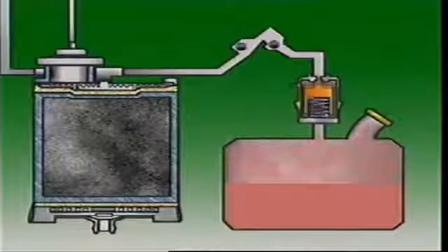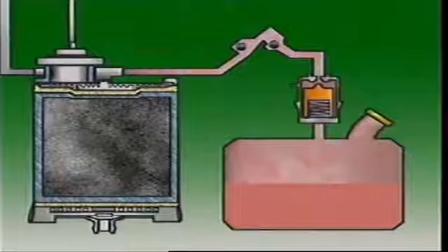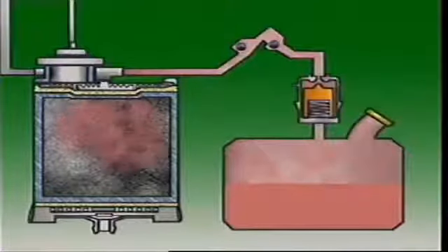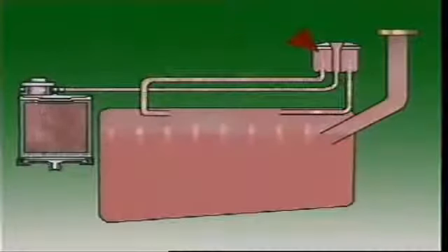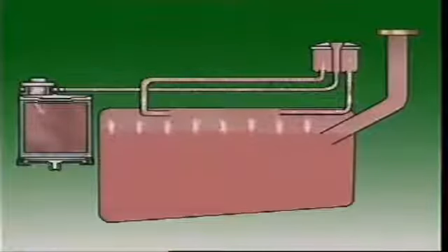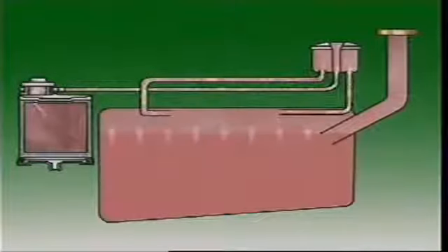This valve opens when pressure starts to rise and lets vapor through, but not liquid. Liquid fuel closes the check valve and blocks the line, stopping liquid fuel reaching the charcoal. Some systems have a small container called a liquid vapor separator above the fuel tank. It also prevents liquid fuel reaching the charcoal. This petrol tank has a small separator tank and a number of vents. They're from different parts of the tank, so that for as many vehicle positions as possible, at least one is always above the level of petrol in the tank.